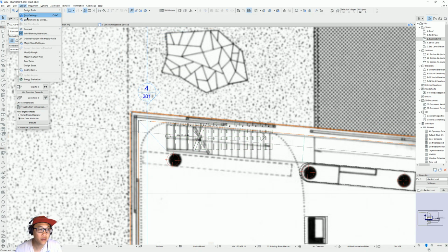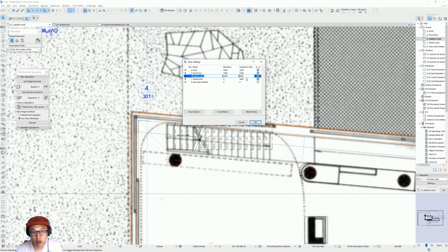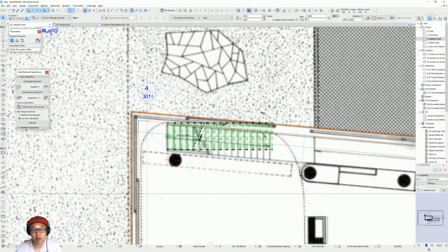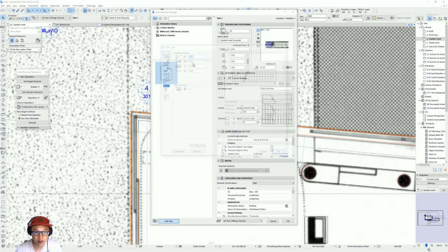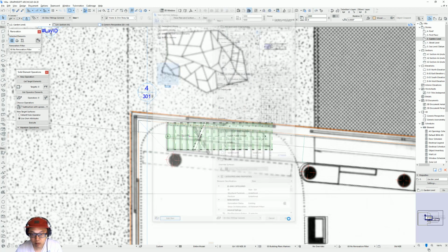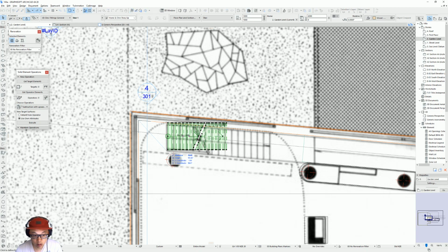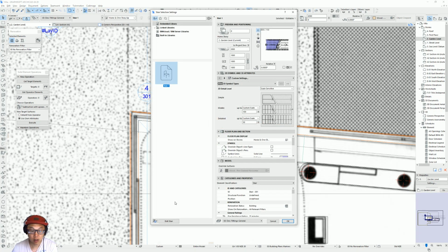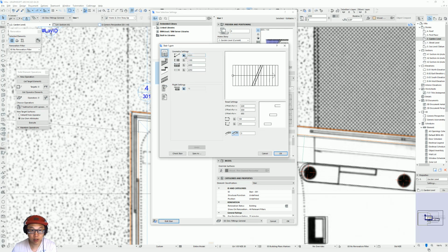Check the story level. So I think between the garden floor, it's 4 meters. Take that again, press Ctrl T, edit stairs, change to 4 meters. It will automatically change this. It's a bit small. So now just measure this 4 point, let's say 4.2. And so we're going to lock that. This is locked. This is to be 4.2. Or maybe this one's 4.2.